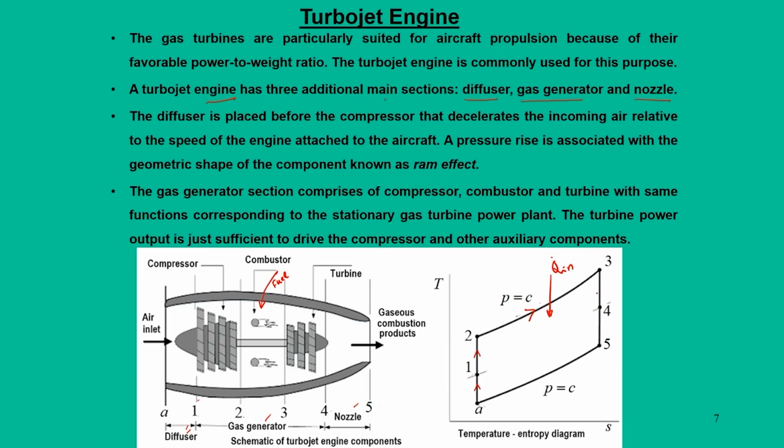When it enters the turbine section, expansion is done in 2 stages, one is the turbine, the other is the nozzle. So, we have 2 sections here, one is from 3 to 4, that is the turbine, and 4 to 5, that is the nozzle.